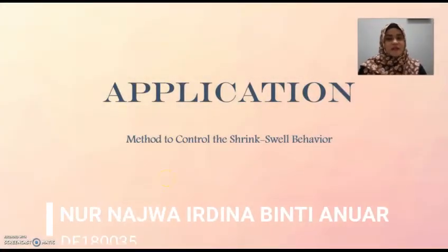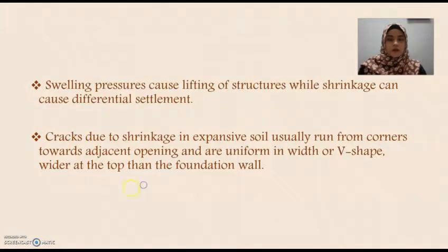Next, let's take a look at the application. The application is the method to control the shrink-swell behavior. Swelling pressure can cause lifting of structure, while shrinkage causes differential settlement. Cracks due to the shrinkage in expansive soil usually run from corners toward the adjacent opening and are uniform in width or V-shape, and it will be wider at the top than the foundation wall.